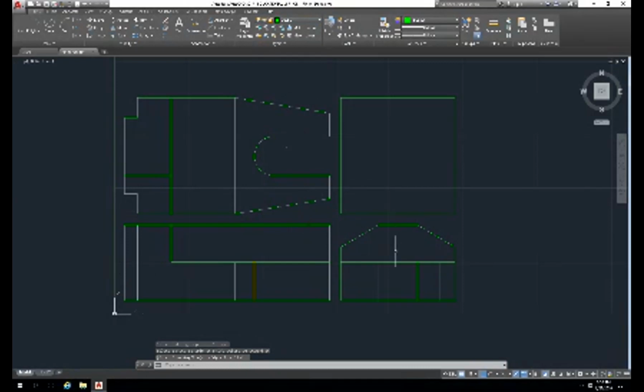And we also need this cutout indication on the right side view. We know that it is 0.40 deep, so I'm just going to draw it with an offset 0.40, enter, taking this object there, 0.40. So now we're going to use extend command and say extend, nope, didn't take it, EX, extend this to,